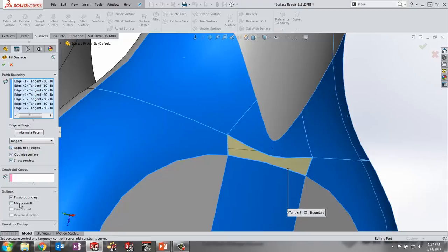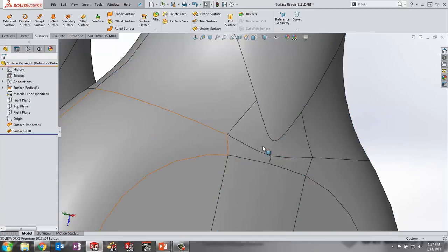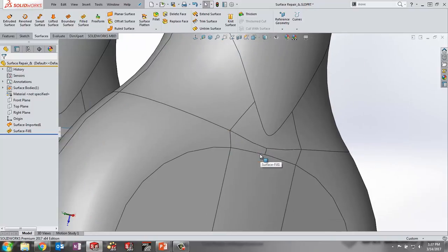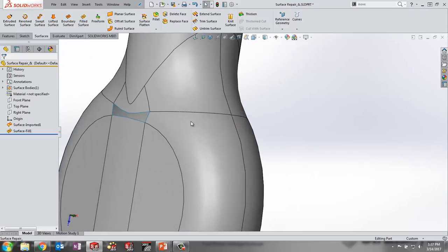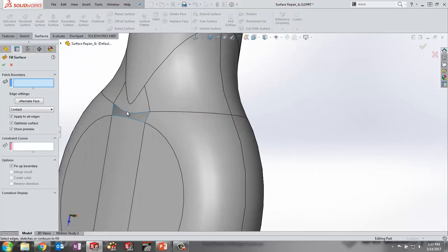We'll optimize the surface, and then if you can, merge some of these faces together. So if you've got a whole bunch of faces in here that would be redundant, let's try and merge some of these together to get the best possible surface that we can with the minimal amount of faces. All right. So it brings that in as 2, just based on the geometry that we're using. We can go ahead and go to the other side and do the same thing.